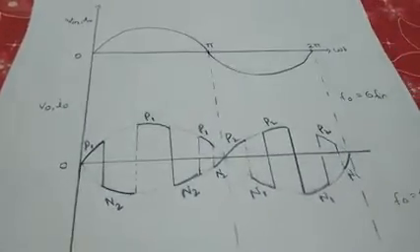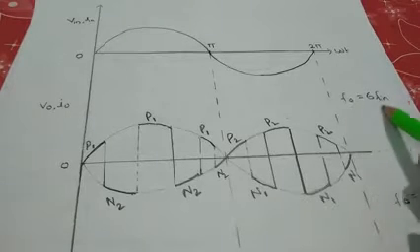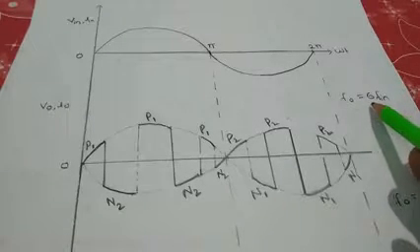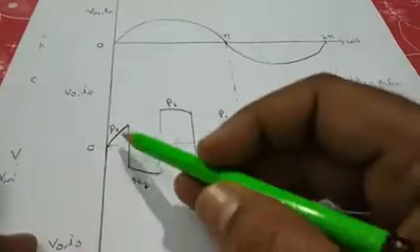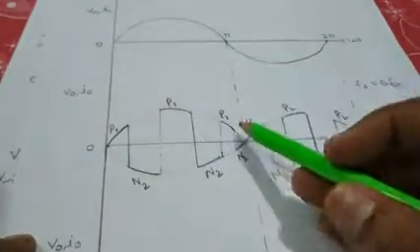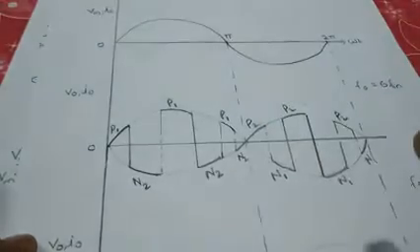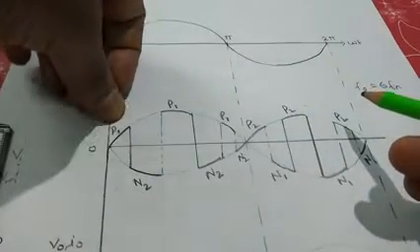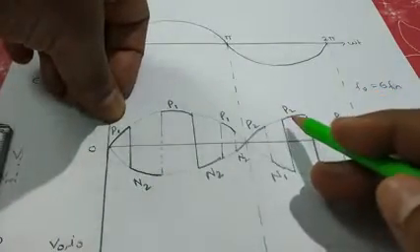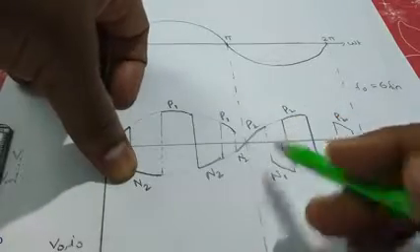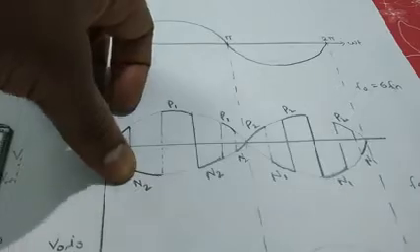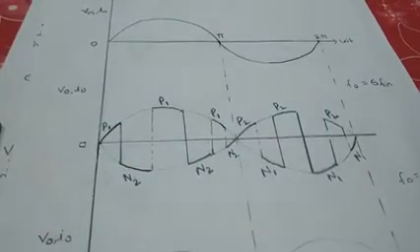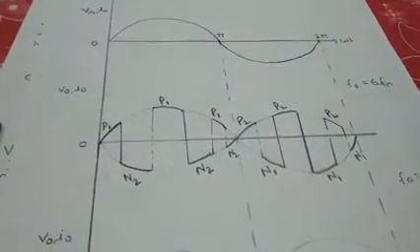So see here, for boosting 6 times the input frequency, we need each SCR to be triggered 3 times. So P1 and P2 are triggered 3 times. In the same way N2 and N1 are triggered 3 times. Then only we will get 6 times the frequency.